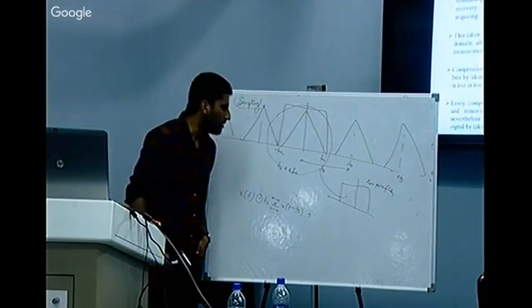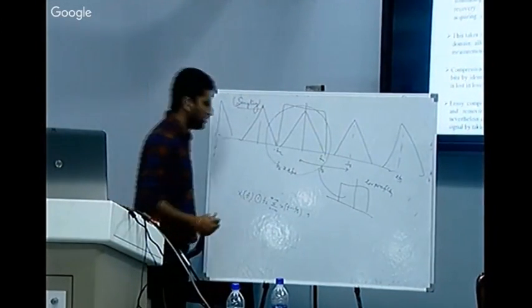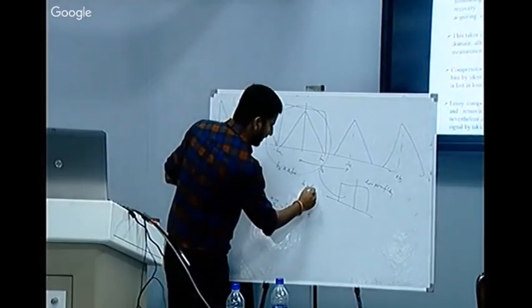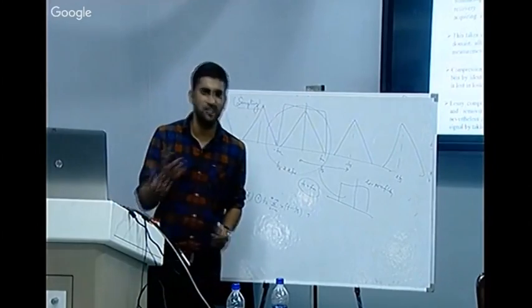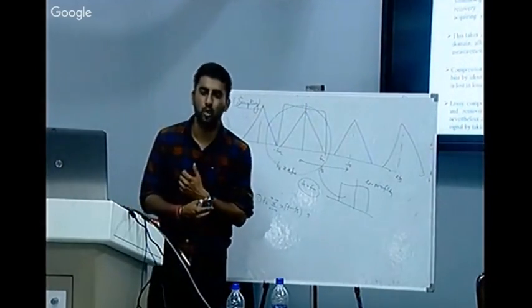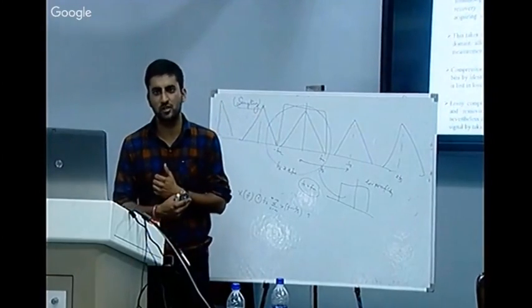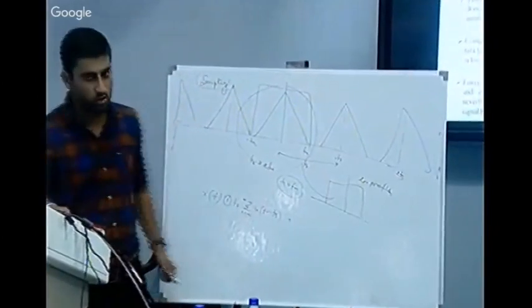Okay, so what we are trying to do is reconstruct this data at this rate, fs equals fm. I know an aliasing problem is going to be there, undersampling is there, but still with the help of compressive sensing, with the help of some probabilistic or statistical functions, we are trying to recover this signal at this rate. Let's see how this is going to be possible.